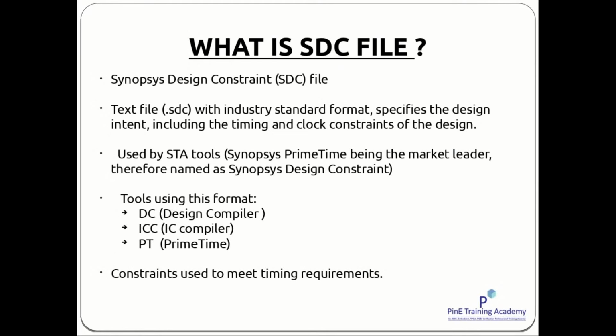SDC is the abbreviated form of Synopsys Design Constraint. It is a text file with industry format, which specifies the design intent, including the timing and clock constraints of the design. It is used by STA tools, with Synopsys PrimeTime being the market leader, therefore named as Synopsys Design Constraint. There are several tools that use this format: DC, which is Design Compiler, ICC, which is IC Compiler, and PT, which is PrimeTime. This file comprises the constraints used to meet the timing requirements of the design.